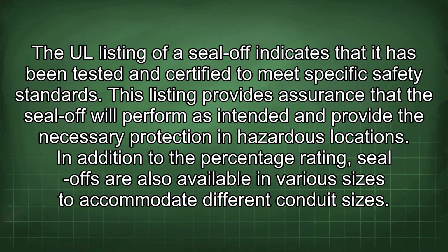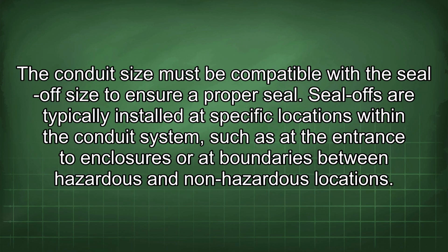The UL listing of a seal-off indicates that it has been tested and certified to meet specific safety standards. This listing provides assurance that the seal-off will perform as intended and provide the necessary protection in hazardous locations. In addition to the percentage rating, seal-offs are also available in various sizes to accommodate different conduit sizes. The conduit size must be compatible with the seal-off size to ensure a proper seal.